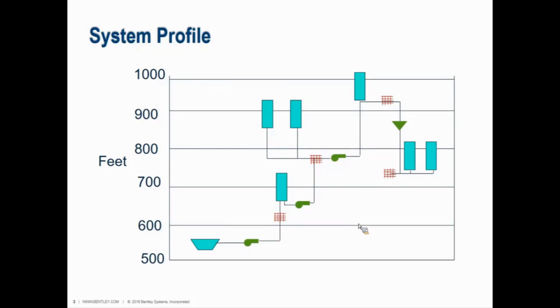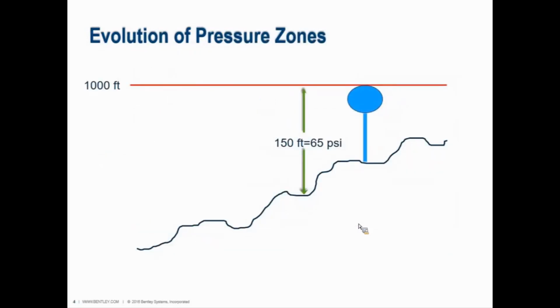Now, you can refer to the system profile maybe as a starting point when you're setting up the model, but of course you'd want to go verify site conditions to make sure that tank water levels are really what they are supposed to be. Now, let's start thinking about how tanks behave and how pressure zones kind of form or